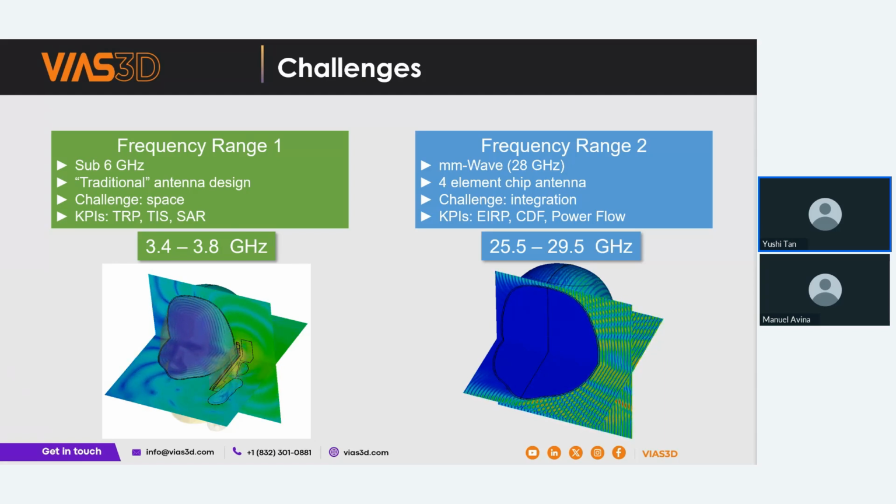When we move over to the 28 gigahertz range, the situation is very different, as you can see from this animation. We can see that the fields generally just stay on the outside of the human body, in this case the phantom model. So we can take some simplifications to make our modeling effort a bit easier. The two key differences here: the model can be exactly the same, but the frequency being different changes the story basically.